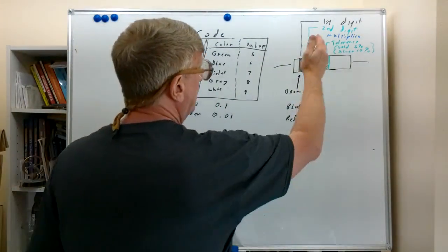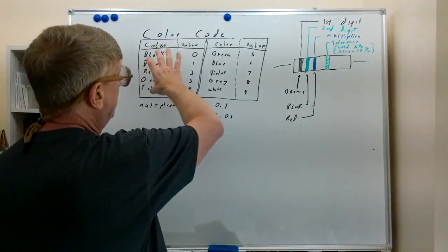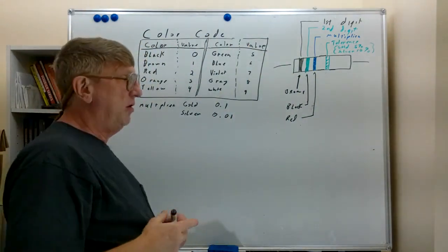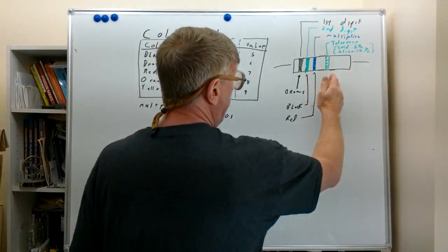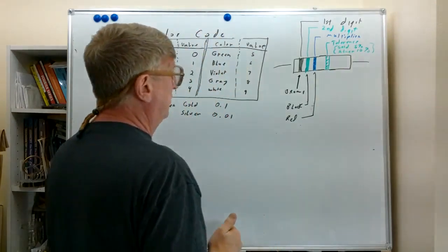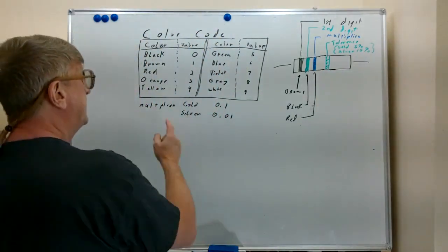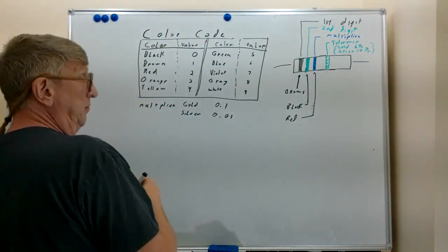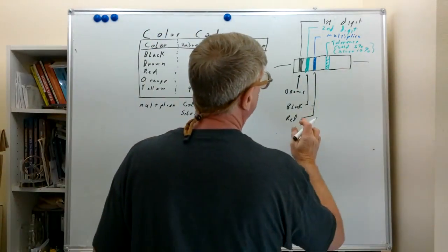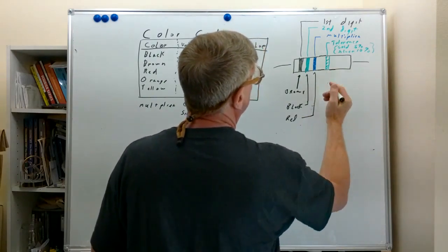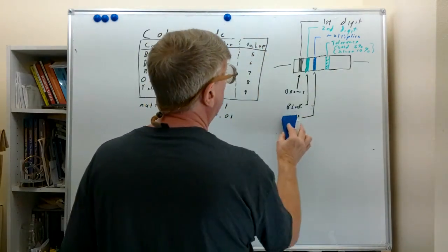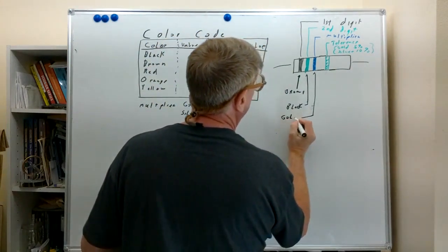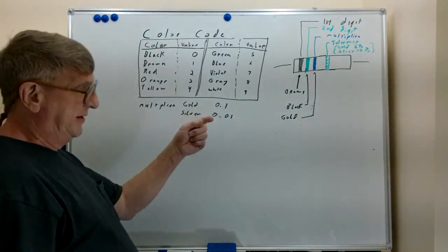And we've talked about multipliers when they fit the black, brown, red, these colors. Gold can be in the fourth band as a tolerance rating, or it can be in the multiplier third band as a multiplier. So if this was gold, that would be a multiplier of 1/10.